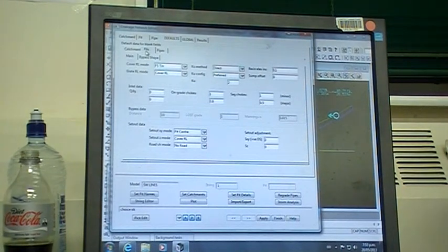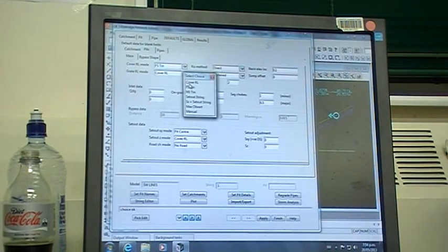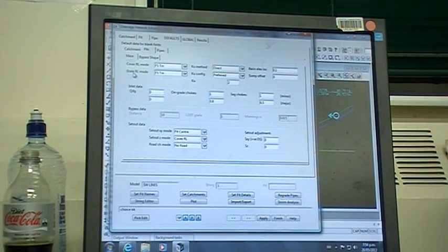Under our pits tab, under defaults pits, we're going to set the cover mode for our manholes. Make sure both of them, the RL cover and the grate RL, are both finished surface tin. And basically, what that's going to do is set the manhole lid at the tin level, at our design level.